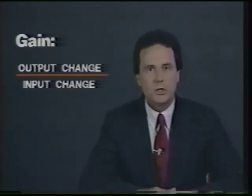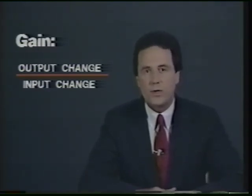Gain can be expressed in terms of various units of measurement, such as inches of valve travel, degrees of temperature, or cubic feet per minute of flow, just to name a few. Gain can also be expressed as percent of change. Each of these expressions identifies an aspect of gain and the corresponding process output change. Using this ratio of the change in output divided by the change in input, the process gain can be computed over any portion of the operating range of a process that has reached steady state.